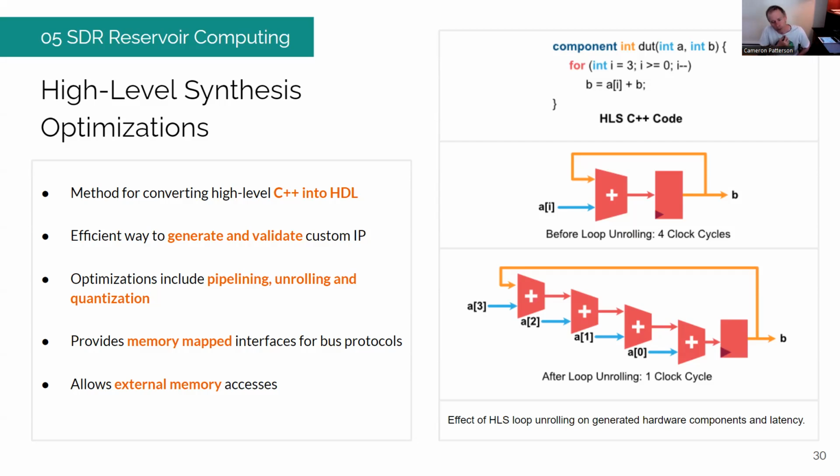And in our experience, if you're doing floating point work, with HDLs you can simulate floating point arithmetic, but very few of the tools actually will synthesize floating point calculations, whereas HLS will do that for you. So, I think it was an appropriate choice for what you're doing.